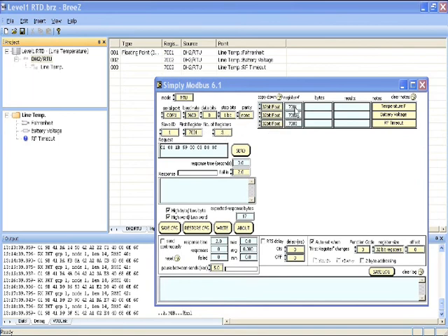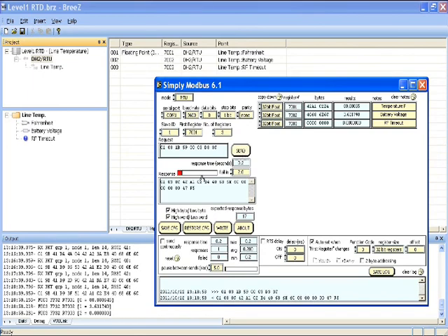I want to ask for exactly the way it's built in the Modbus list, being temperature Fahrenheit, battery voltage, and RF timeout, exactly as I have this laid out. And then I will send this Modbus request. Notice when I do, in the debug window, the response is returned with a Fahrenheit temperature, a battery voltage, and no RF timeout. Notice that my Modbus master is also populated with the same information.